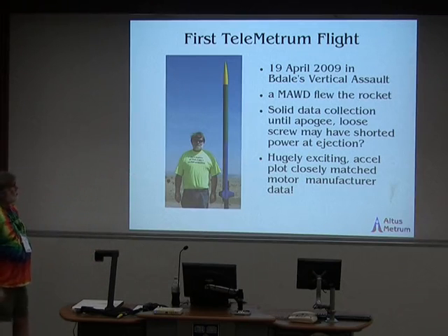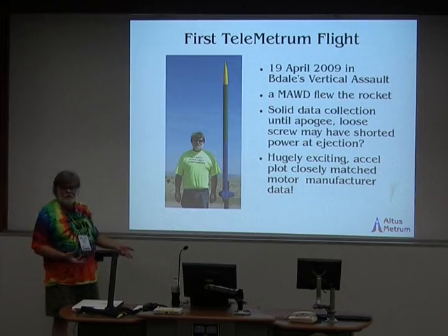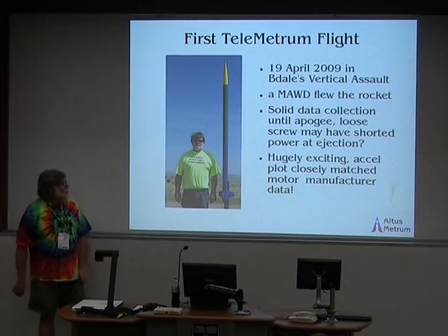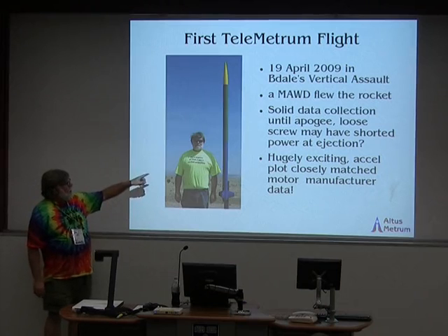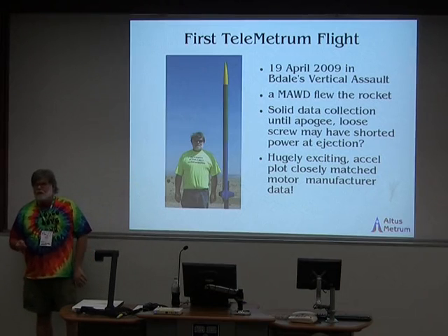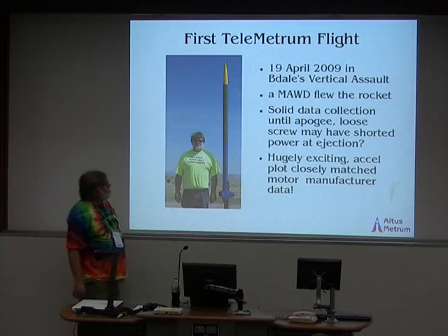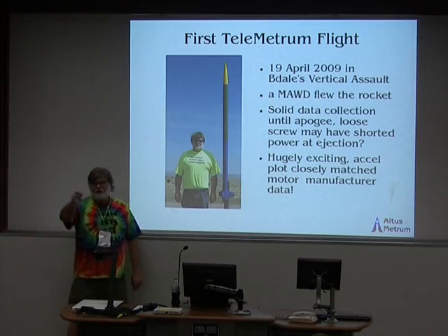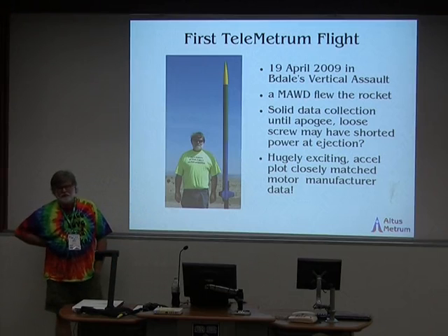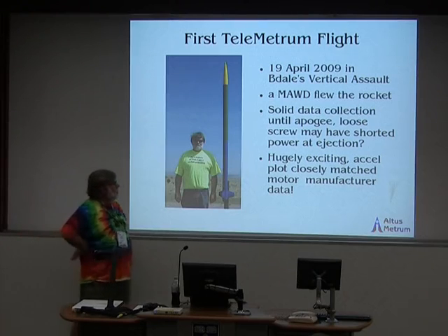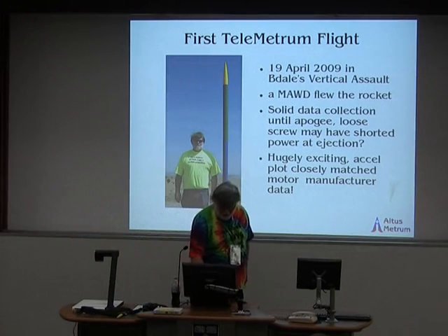And when I got the airframe back, because it did, in fact, recover successfully, when I opened it up, one of the metal mounting screws was just missing. And, you know, the best theory I have is that it came loose and went rattling across the board and shorted something and caused a processor reset. No way to prove that. But we've not yet ever had anything else happen that would cause me to believe that something else was going on that day. Anyway, that was immensely exciting, and we got real data.